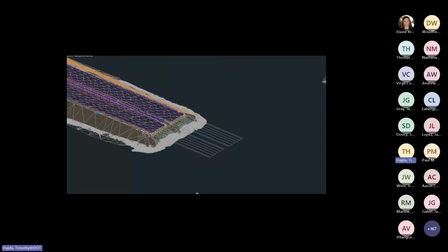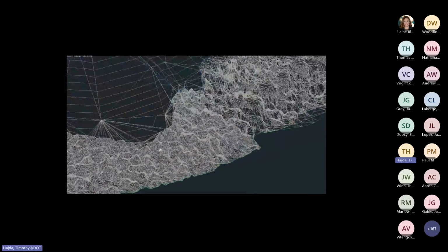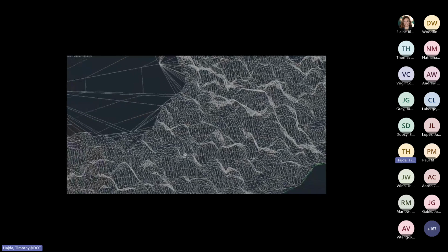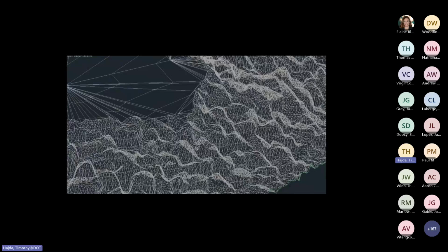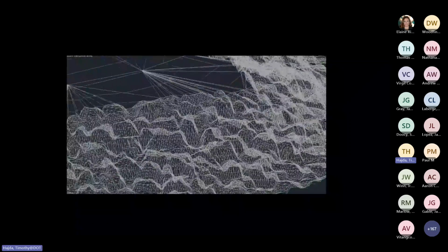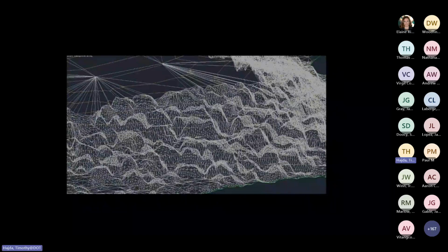And so by adopting and combining these 3 reality capture platforms and our suite of feature extraction tools, we're able to deliver a design grade surface efficiently while really minimizing the amount of time that our staff were out on the shoulder of the freeway. And there you can see how detailed the final surface was of those boulders.